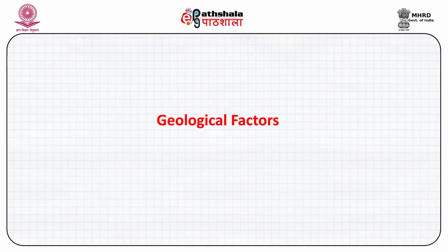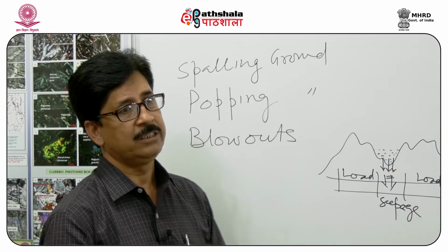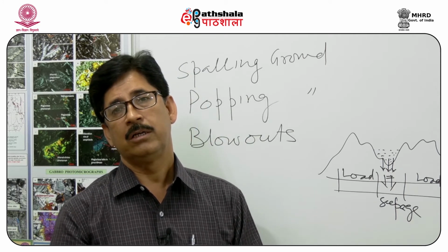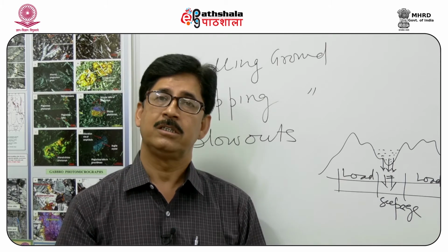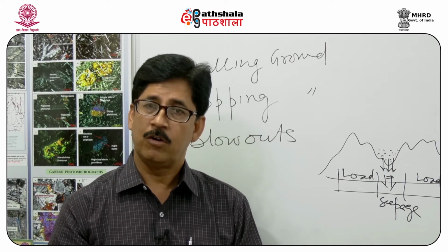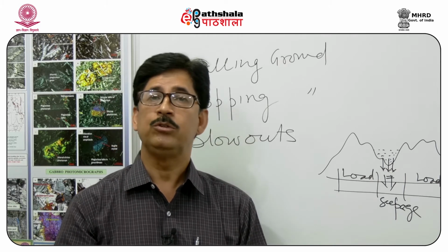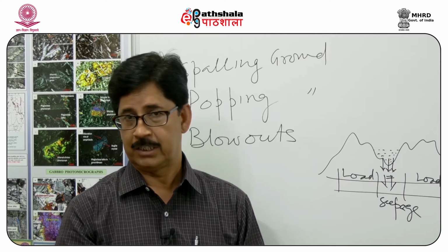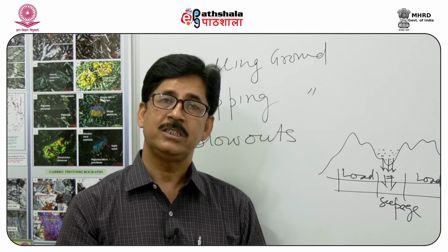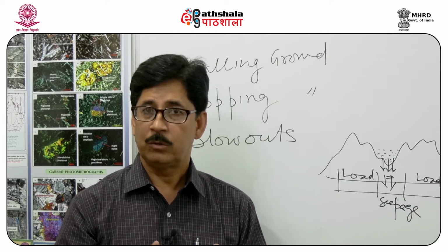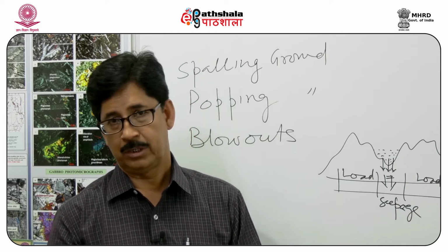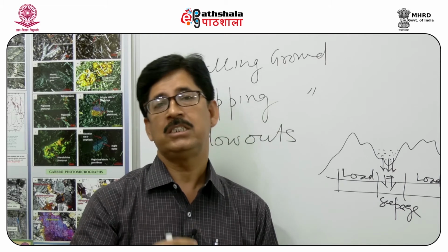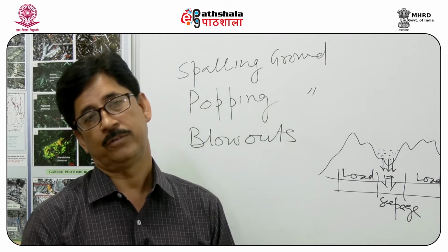As far as geological considerations are concerned, there are various aspects starting from rock type, weathering state of the rock, structures present in the rocks, and the presence of groundwater in the rocks. All these are going to have a profound control on the construction of tunnels. If you have a sedimentary rock sequence, the rock will be somewhat weaker, you may need more support, but the ease of excavation will be more. The rate of advance of tunnel excavation will be more if you have softer rocks.